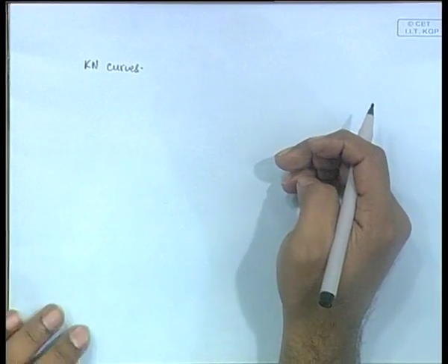And we use a simple definition of a kind of ship we call wall sided ships. It just means the sides are straight, they are called wall sided ships. Of course, all the derivations I have done so far are for wall sided ships. I have never defined anything else, so it does not matter, but you should know what a wall sided ship is. In general, a ship is very rarely like this, it is like this: it will have some bulging. None of that is considered in a wall sided ship because the mathematics is all for straight lines. Okay.